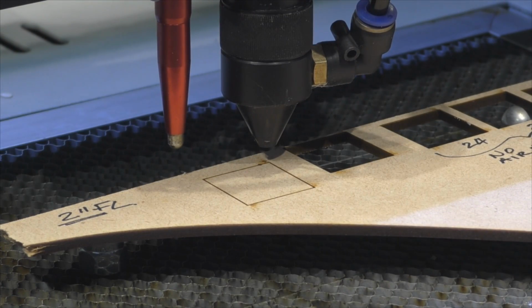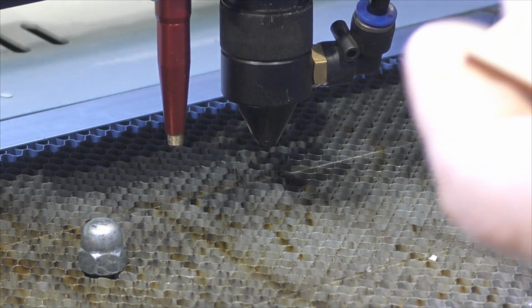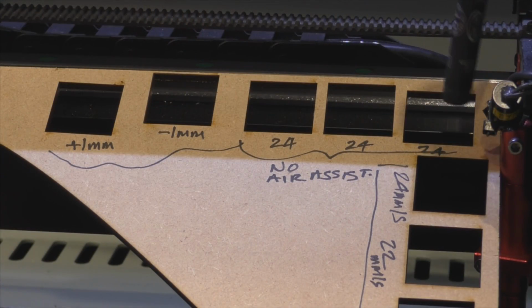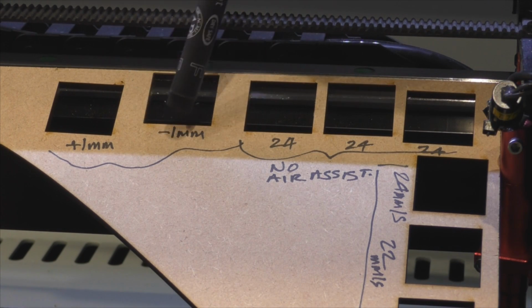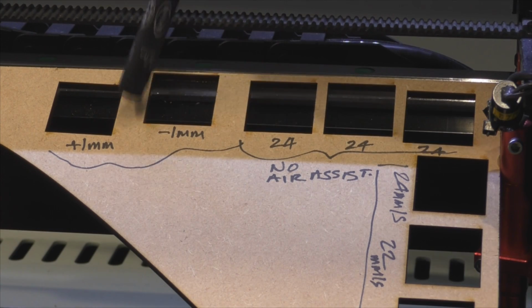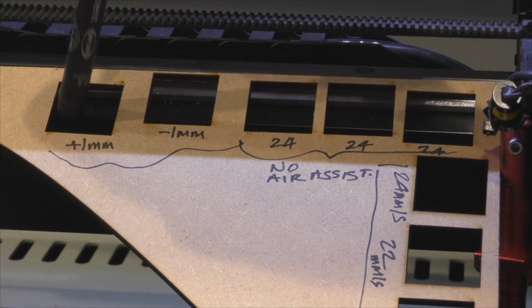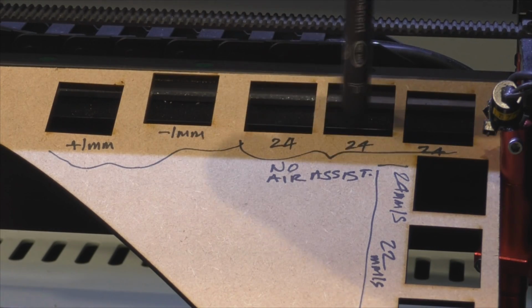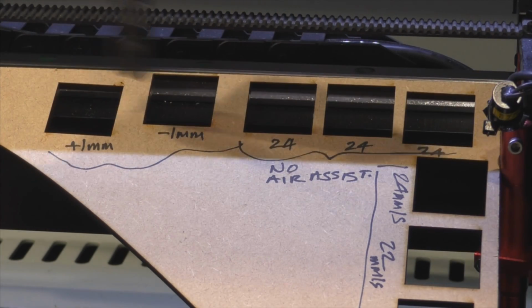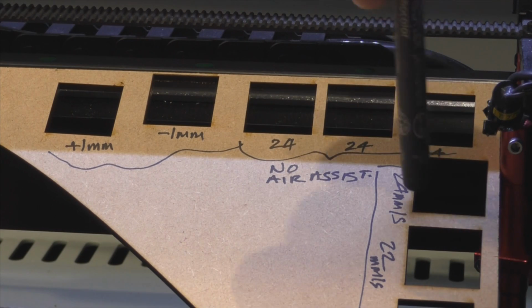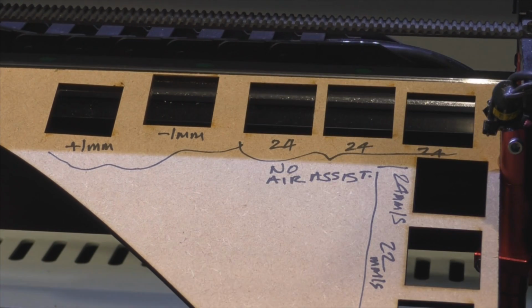Well, we certainly didn't get any flames that time. The product just about falls out still. So we seem to get the best results when we took the air assist off. Certainly -1 was giving us flaming, and it was only just making it through, but then again it was only just making it through on all of these, so whichever one of these we chose, it was right on the limit of cutting. So we've reached that limit at 24 millimeters a second.